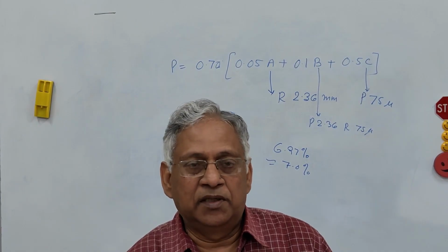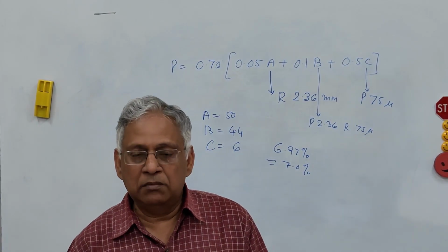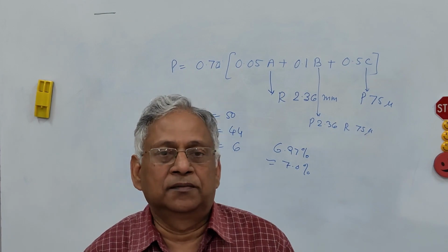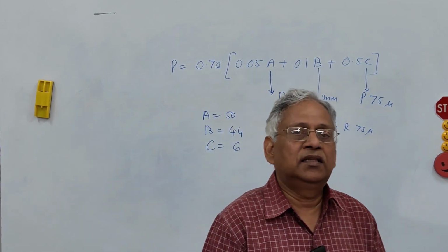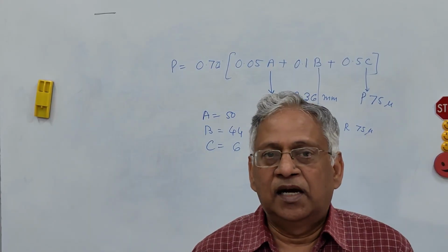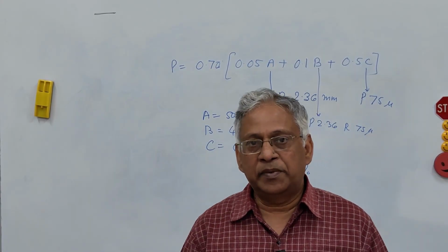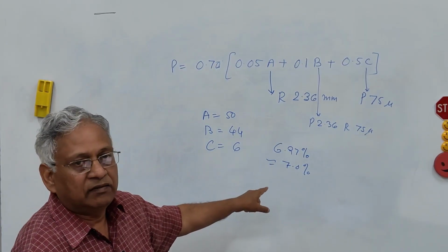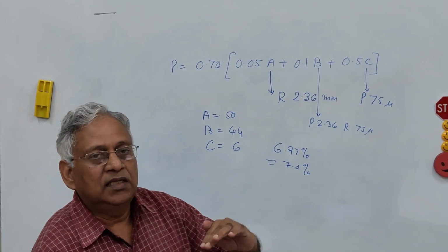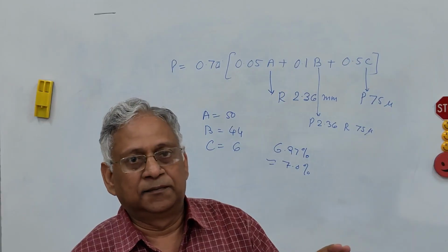Now the next step is to determine the optimum water content at compaction. Marshall specimens are used to determine the level of compaction here, and these specimens are prepared using the same amount of emulsion, that is 7%, but now the water content is varied.